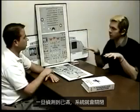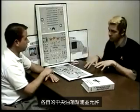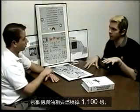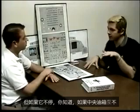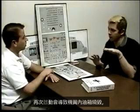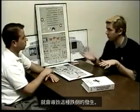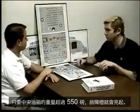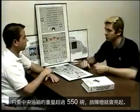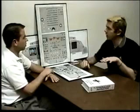Once that senses that it's full, the system will then shut off the respective center tank pump and allow that wing tank to burn down 1,100 pounds. But if it doesn't stop, and if the center tank pump doesn't start up again, and it allows the inner wing tank to burn down, it'll then cause this fault to occur. The fault light illuminates whenever the center tanks are greater than 550 pounds, the wing tanks are 11,000 pounds or less, and